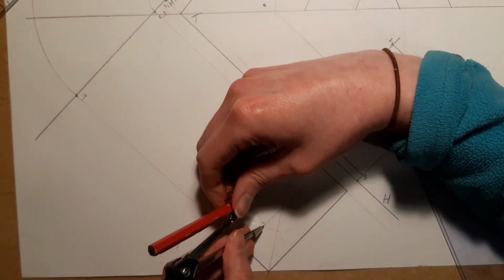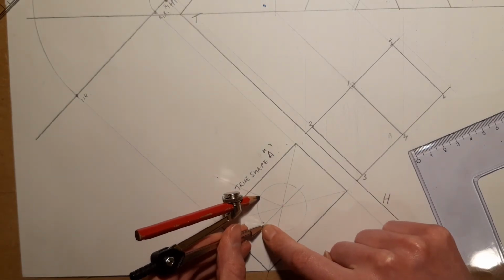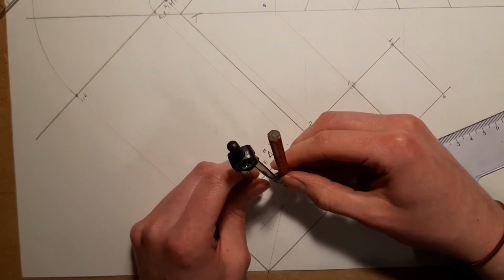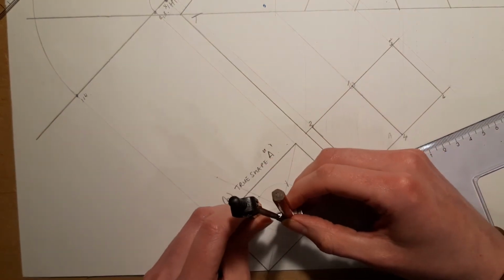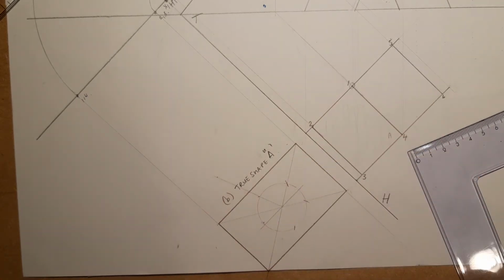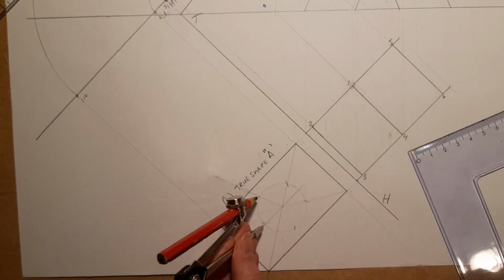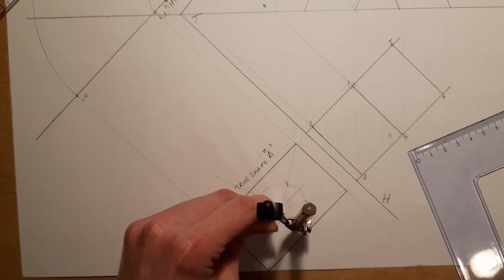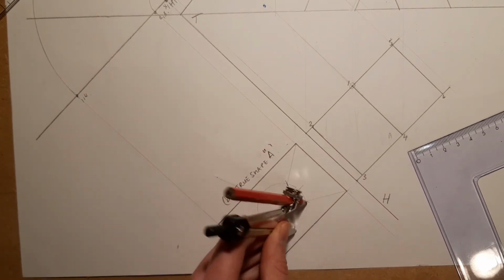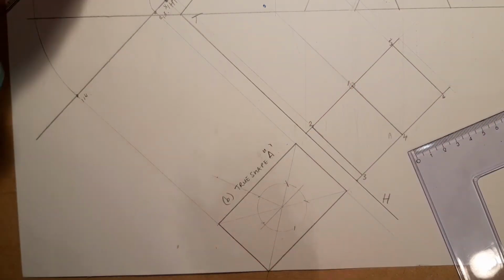So if you take the edge length, that's the distance from the apex of the pentagon to another vertex. So take one of the distances and just step it off the 5 times. And you can see I'm working on this symmetrically. What I mean by that is I'm keeping this centre point as the main one. So I went left and I went right. I went from the new point down and from the other new point down. So it means that these are definitely the same distance apart, even if my accuracy wasn't perfect.